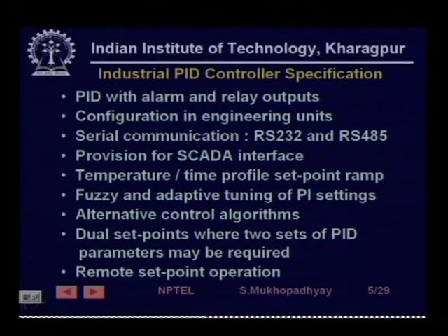So, such facilities have been provided here. And finally, you could have remote set point operation, where this remote set point is actually a subset of SCADA. So, if you have supervisory control from a remote place, then maybe the operator sitting in the control room can give set points. Okay. So, this is what a typical PID controller looks like,